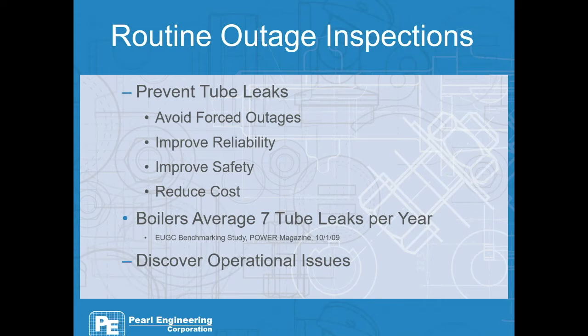Anytime that you come down for a forced outage, there's a huge rush to try to get the repair done as fast as you can and get it started up. If you can schedule your maintenance so that it takes place during your scheduled outages, your facility can see a safety improvement. You're also going to reduce your cost of scrambling a crew of boilermakers on site. Your fuel for startup is a waste, and your facility is going to have lost revenue while your main boiler's down.